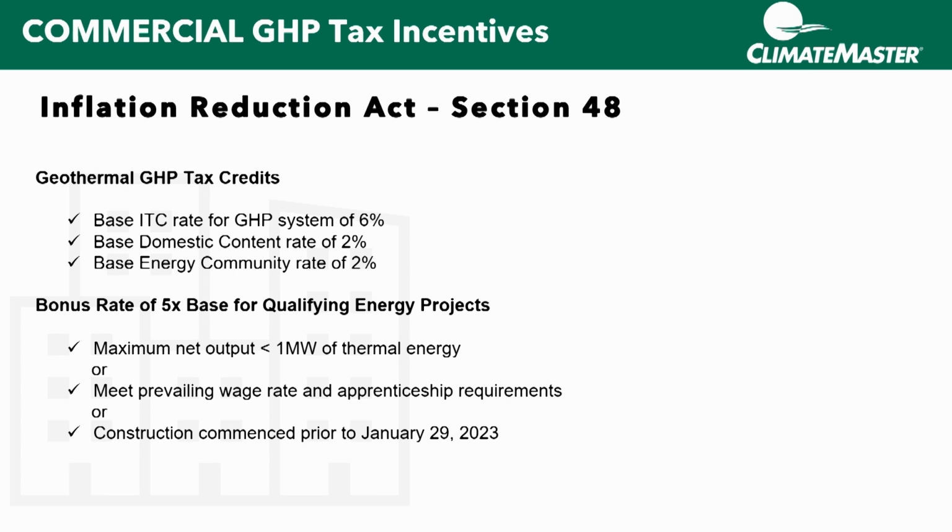So a building with less than 285 tons of what's called, quote, nameplate capacity, which we have asked that they view as looking at the mechanical equipment schedule on the plans, or someone would submit in a retrofit a mechanical equipment schedule, and you'd have the rated capacity under the conditions for that project, and you'd look at the rated cooling capacity. That would be the size of the system. So you add it up and convert it into tons.